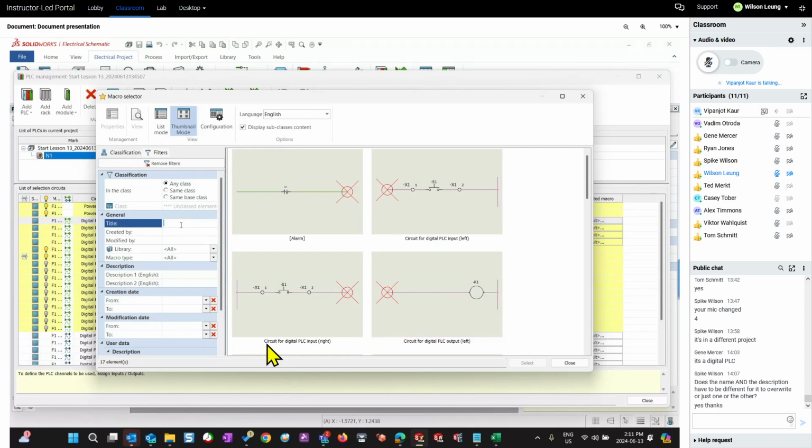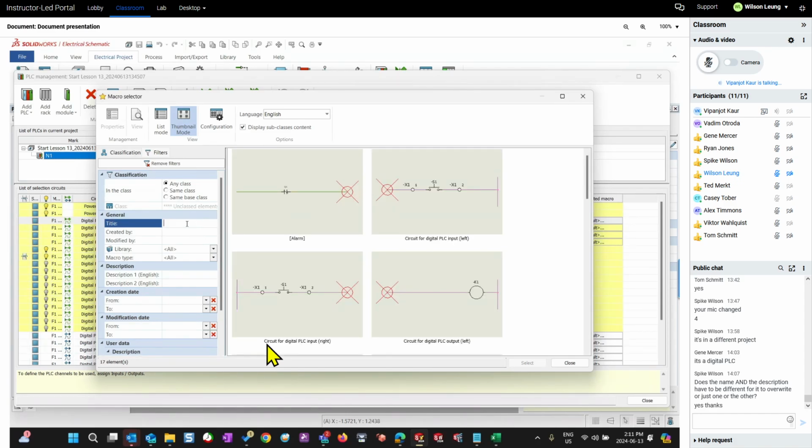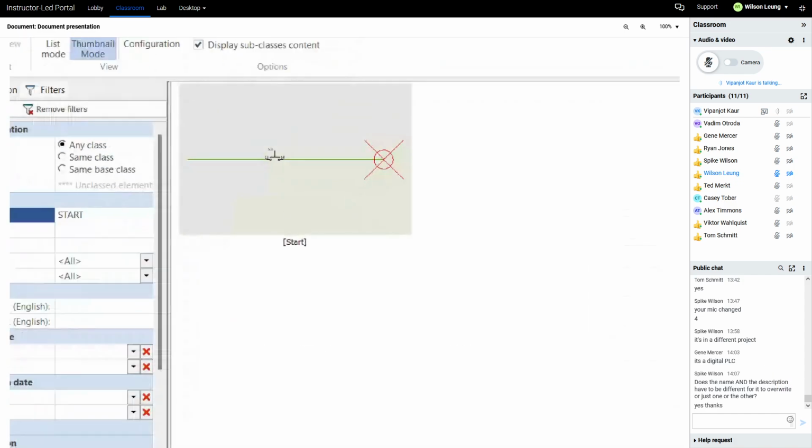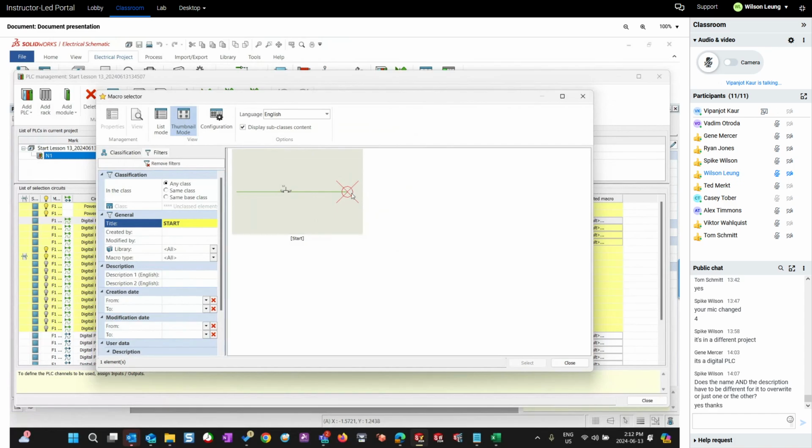Look on a picture on page 259, a big yellow picture right on the top. So the name of macro is start macro. Hey, look, I'm putting my insertion point. Ooh, start. Look at that. They told us we put a symbol for the inputs on the right of the page. So this macro has insertion point here, so it can perfectly snap my connection point for each circuit. So insertion point is on the right hand side. So I'm picking a start button.